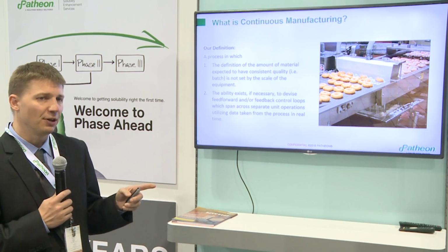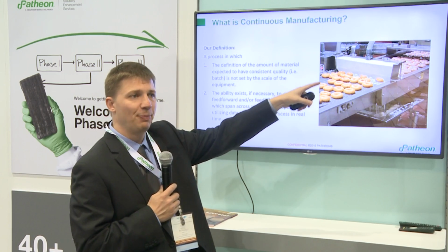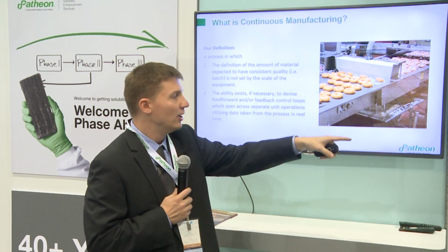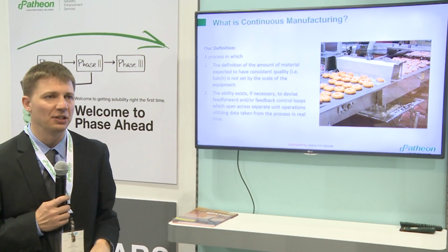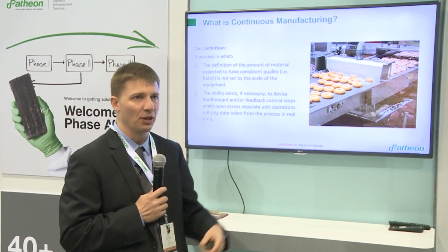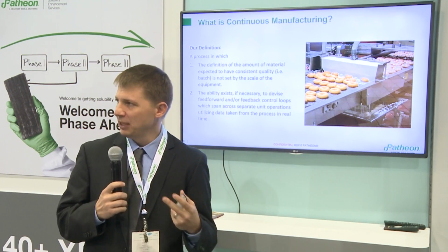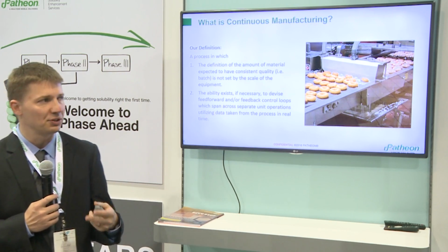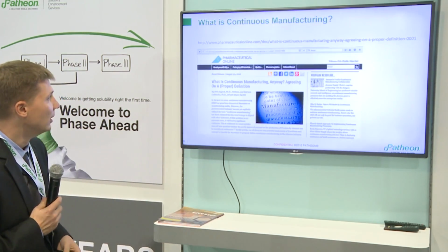What continuous manufacturing will let us do is, since the donuts are coming out right there, but they're also being cooked just a few minutes later, if you start to see a problem with your donuts down the stream, you can go back and you can adjust the temperature in the oven or the temperature in the fryer or whatever the case is. It gives you that ability to actually update your control in real time, and monitor your process from across the entire process while you're running.